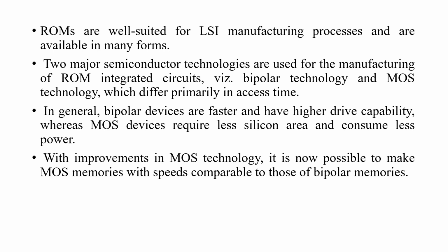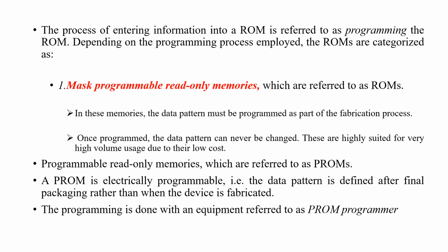With improvements in MOS technology, it is now possible to make MOS memories with speeds almost comparable to those of bipolar memory. The process of entering information into a ROM is referred to as programming the ROM. Depending on the programming process employed, the ROMs are categorized as: first one, mask programmable read-only memories, which are referred to as ROMs.